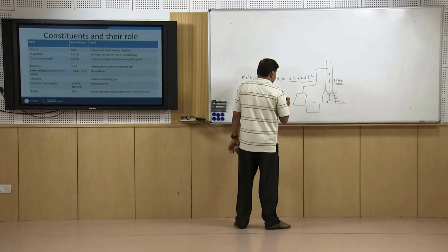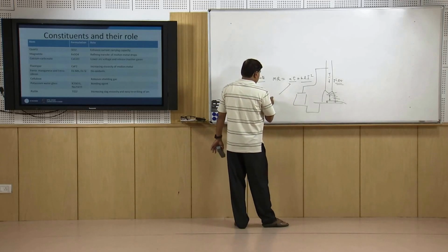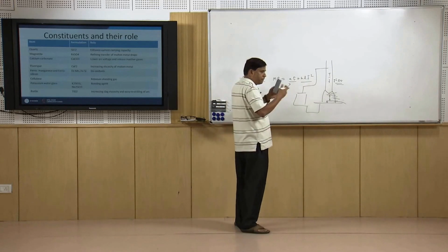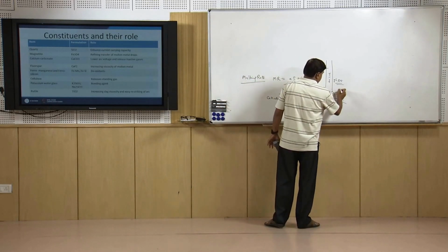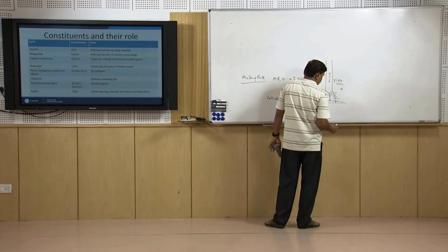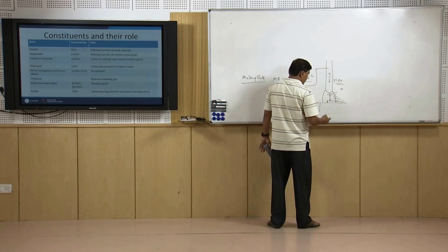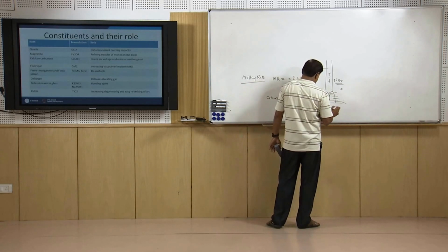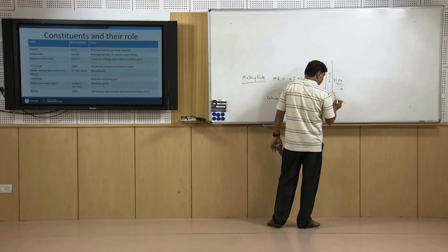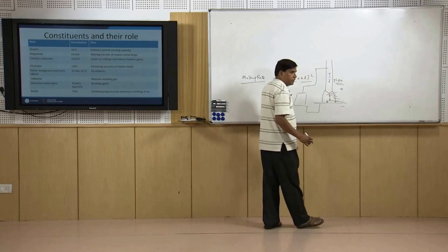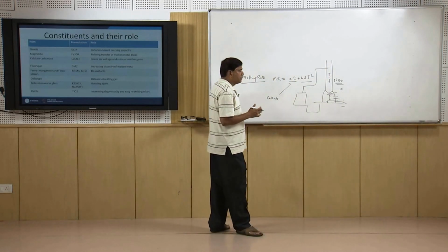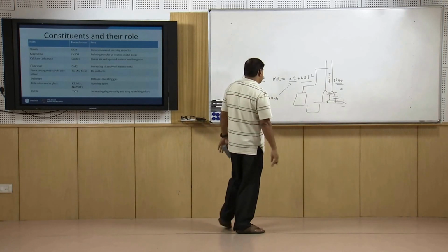One heat generation comes from the cathode drop zone or anode drop zone, as per the polarity being used. If the electrode is connected to the positive terminal, then the anode heat is considered for melting of the electrode, and the cathode heat generated in the cathode drop zone is attributed to melting of the base metal.